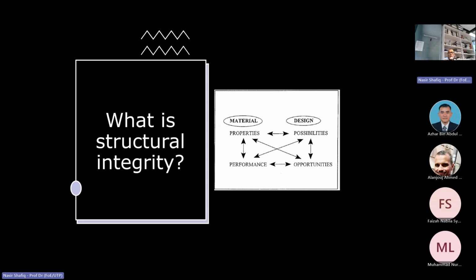And for that 20 mm, you have chosen X65 pipe. For X65 pipe, you refer to the yield strength, the ultimate strength, the ductility factor. So we play in integrity analysis, material and design.